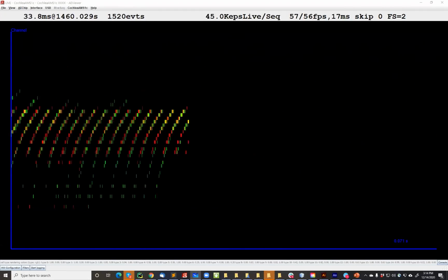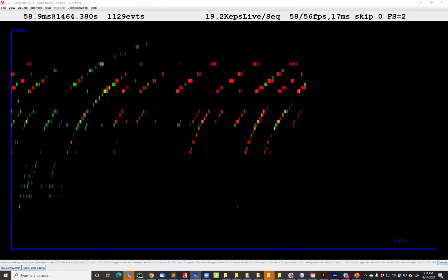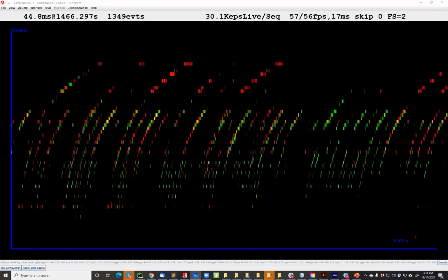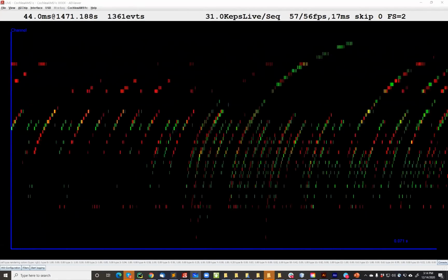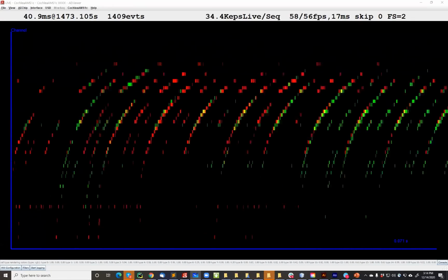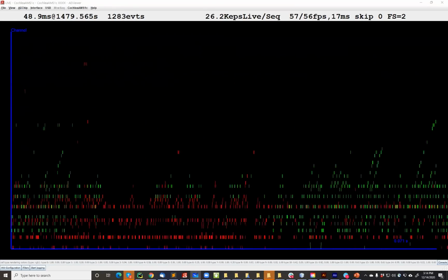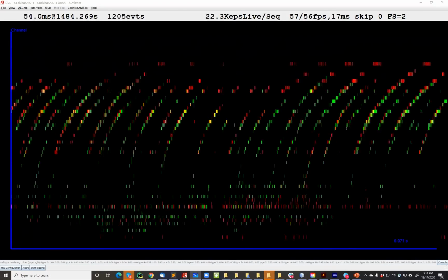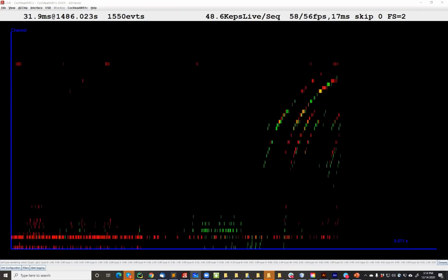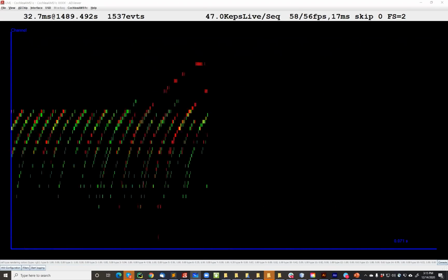You can design an actual bandpass circuit, but what's nice about having this feedback is that you can tune the Q of the filter. You like to show, okay, now I have a filter that's kind of broad in tuning, and then you set the biases so that you see a less selective filter, and then say, okay, let me turn it up so that the Q is higher, and then you see a sharper filter. Okay. If you know exactly what you want, then you can just design it right in, without allowing for this variation.